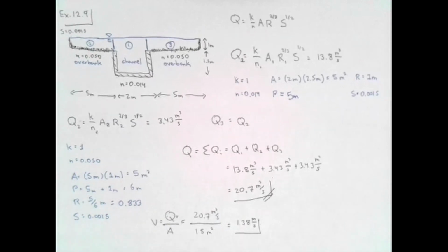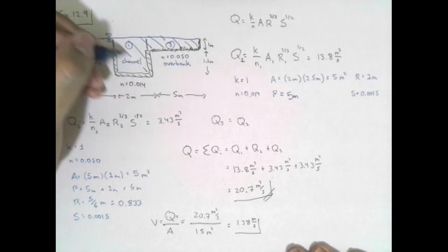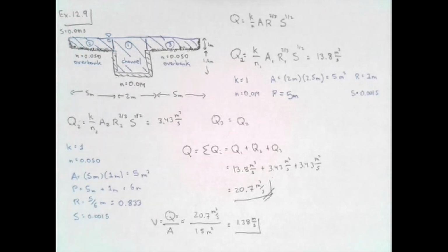Now, why do you think it would be important to calculate individual velocities? Why can't I just say that I have an average velocity for the whole thing? Why would I need individual ones? Because your velocity of fluid over a certain surface will affect the performance of the fluid over that surface. Exactly, right? And then from a more engineering standpoint, we can also think of shear stresses and erosion, right? Erosion is directly related to the velocity.